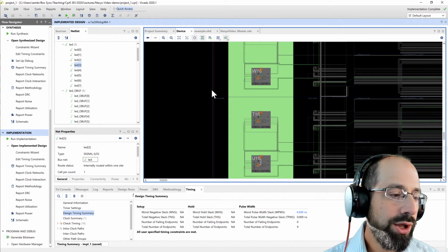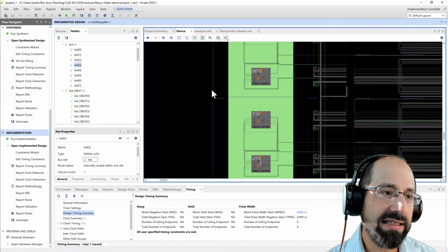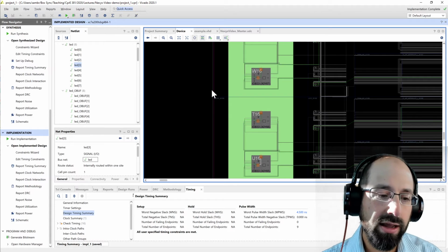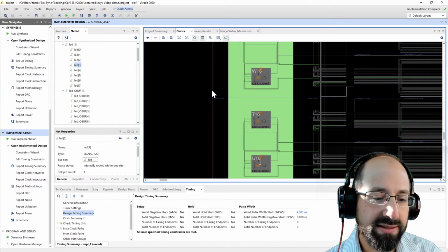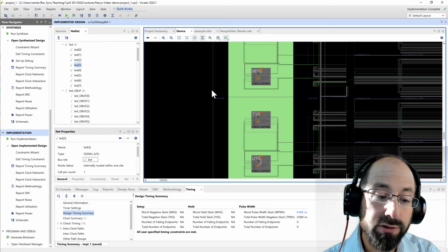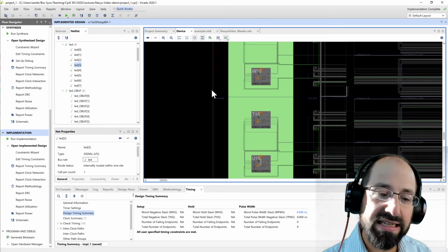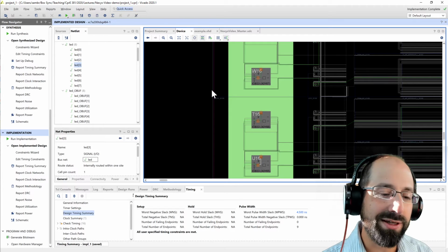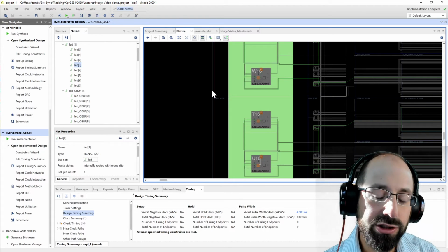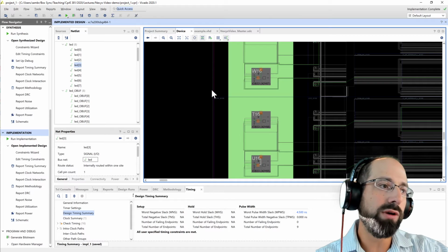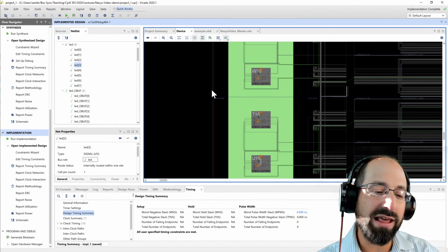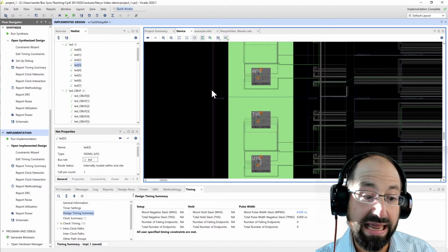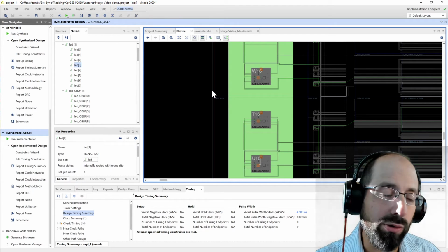And for that reason, while for our design it really didn't take that much time at all, again, it's a pretty simple design. It probably didn't try that hard. Synthesis can take in complex design 30 minutes, 40 minutes, but it shouldn't for the designs in this class. Place and route can take hours. Usually, if it's more than 12 hours, something is very wrong in your design by and large. But as you start to use more and more of your FPGA, and it has to try that much harder to kind of get everything to fit and to try to make constraints, it can take on the order of hours and hours.